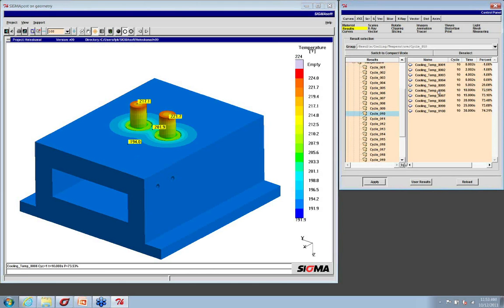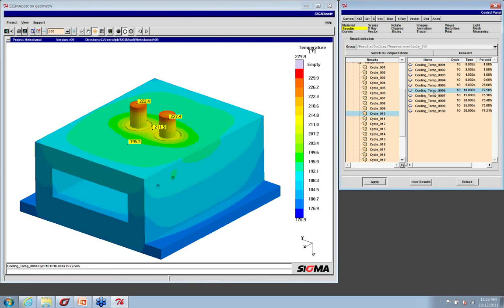Now if we even go to the 10th cycle, again, pretty big difference there, and there are multiple points of value here. One is to look at the mold like this and learn how to design your cooling system the best way possible to pull that heat out. And then of course the other side of it is making sure that we have the right conditions so we predict our filling, our packing, and our solidification phases properly, and really get a much more accurate understanding of what the shrinkage and warpage or stresses in the part may be.